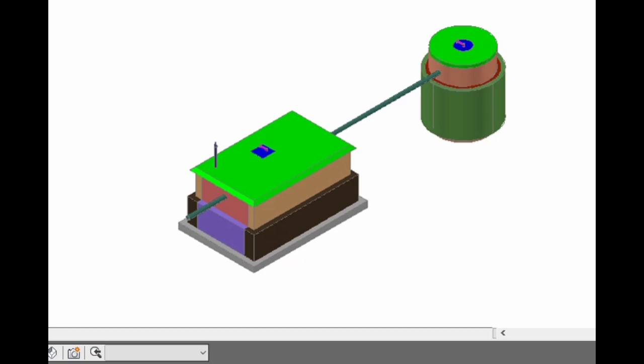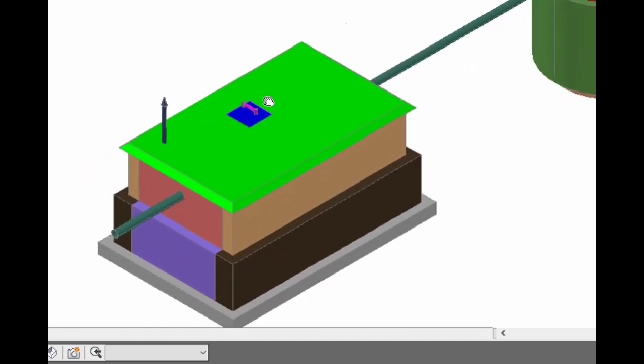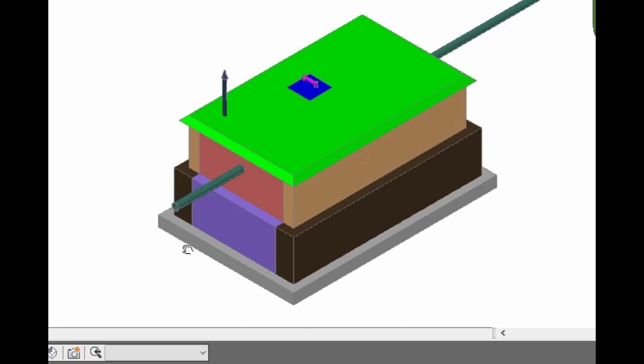Now, you can observe the septic tank first. This is a concrete bed that has been placed. Over this, the first step of first class brickwork is constructed. This is the long wall, the short wall here. The second step, the precast RCC slab, is placed over the structure up to above the ground level, and an opening has been provided here. This is a vent pipe that you are observing. Let me show you one by one how the construction could be done.